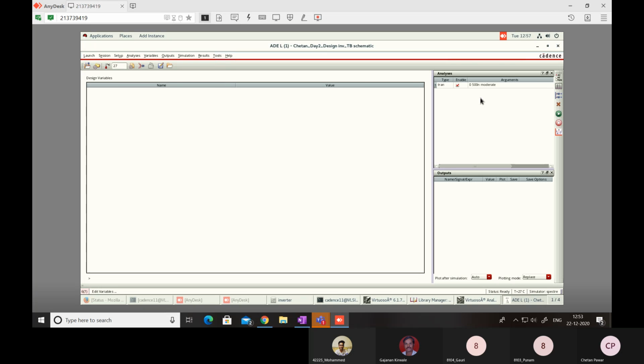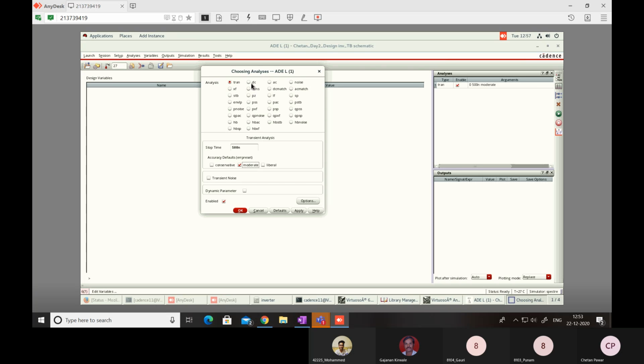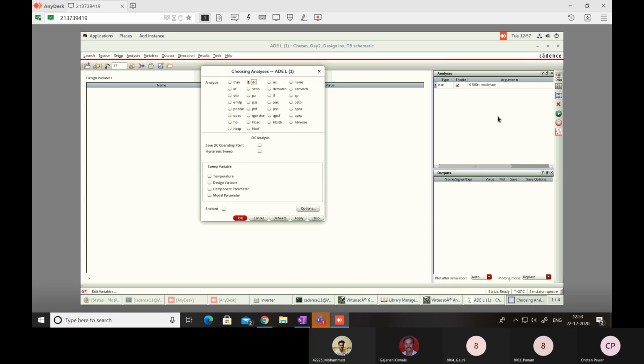Okay, done all. Okay, all of you done. The analysis gets added in your analysis window, right? Similarly, if you select DC here, you can select DC analysis also. Choose analysis, DC analysis. Like this also you can do. Save DC operating point. Mohammed, choose analysis.